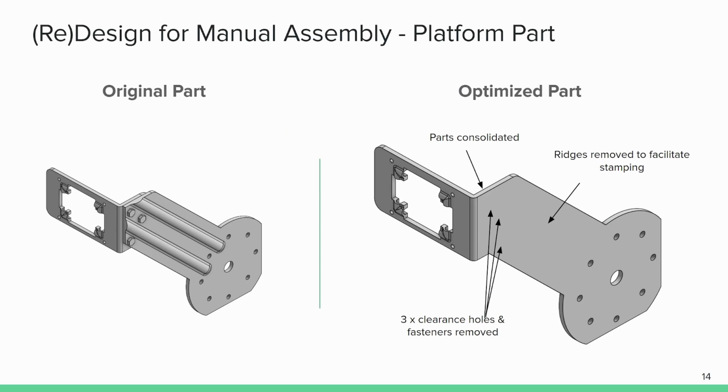The part that we decided to redesign is the roller support and the bridge support, as these parts are both of high functional importance according to our quad chart, which by consolidating we reduce the total amount of critical failure points. It also spreads the cost of the bridge support, which is a high cost part according to the quad chart, to the roller support, which is a low cost part, ultimately decreasing manufacturing costs.